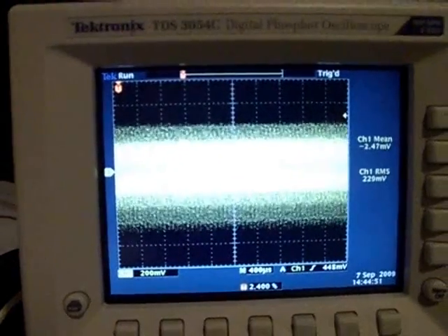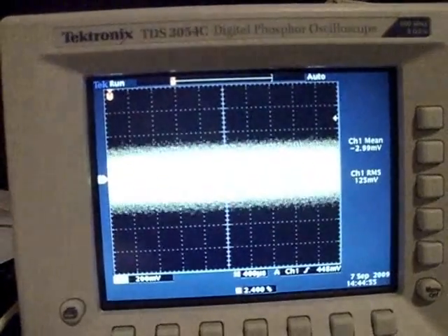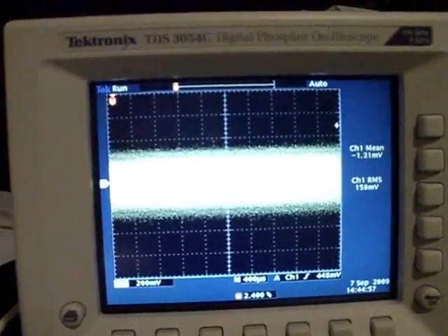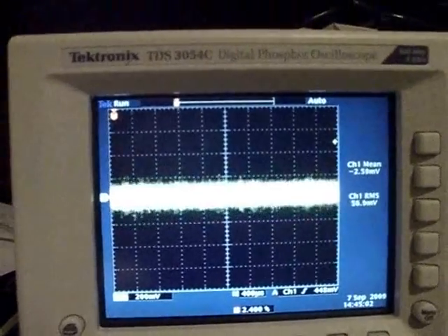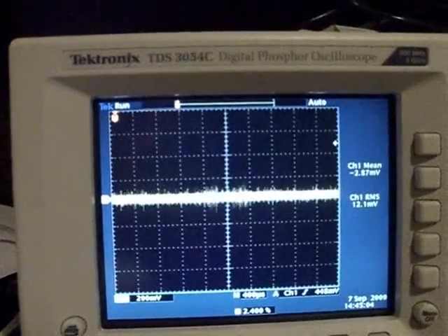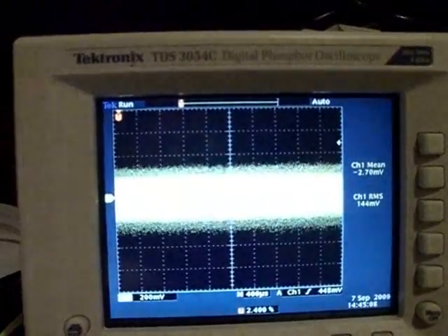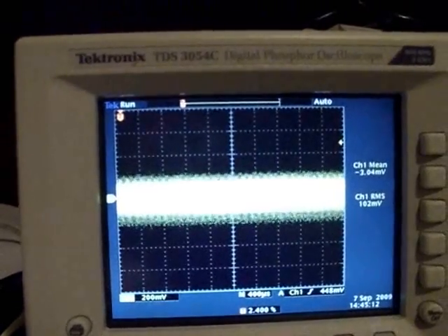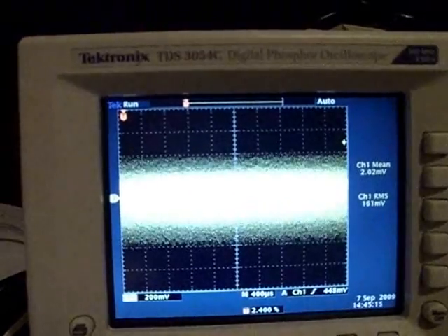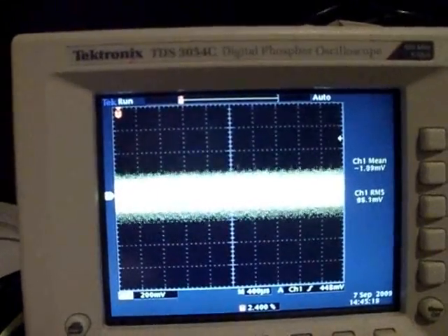And then if I mess with the on time, well, here I'll set the off time to, let's just say, that peak right there. Now I'm going to increase on time. I'm decreasing on time. Okay, nothing. Now I'm going to increase on time. Increasing, and see it shrinking down. Increasing, and now it's growing again. See, so there's a whole bunch of these little nonlinear zones.